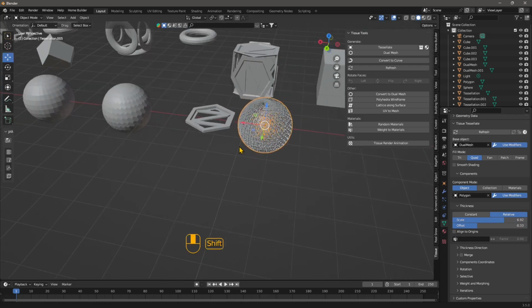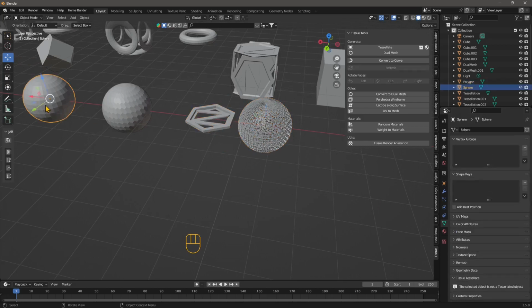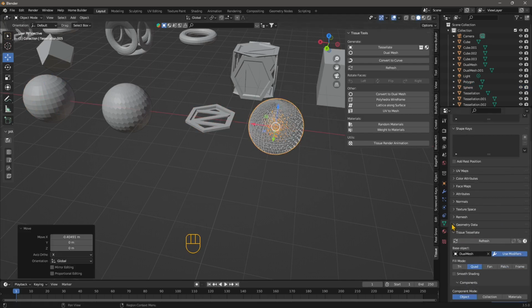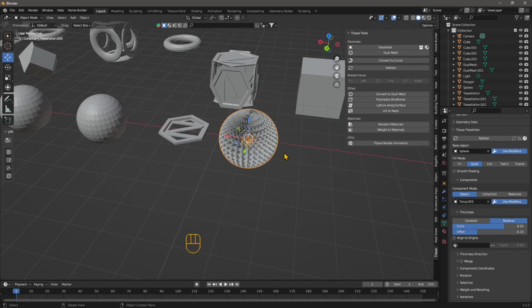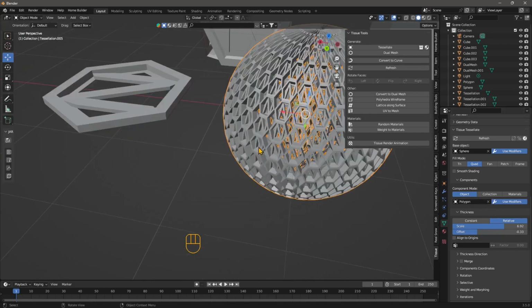And you can also change the source element and the surface. So if I select this, go back to the object mode, you can delete the polygon and delete the base object. So here you can reassign another object. So let's use this other sphere. Let's keep it on quad. And here I can select another component. So it can be this one. There you go. So this is the result. Or let's delete it and take this one again.